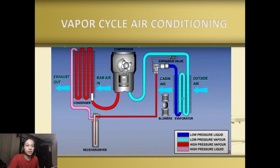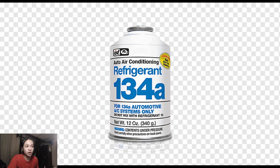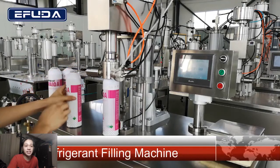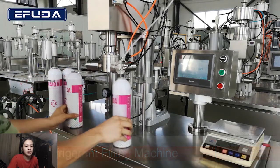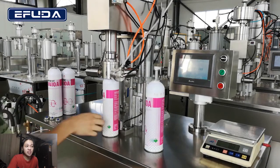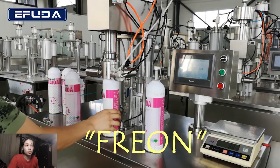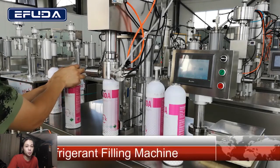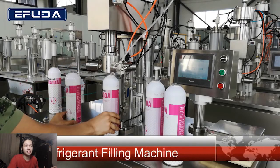The vapor cycle air conditioning is a process similar to those air conditioners at home and those used on cars. Should note that this system only cools the cabin of the aircraft and it does not pressurize it. The refrigerant used is called tetrafluoroethane or R134A, which is circulated through the tubings and the variety of components inside the closed system. Regardless of the manufacturer, the refrigerant is most often called freon, which rapidly absorbs the heat energy from all surrounding matter, which is why it is used in this air conditioning.